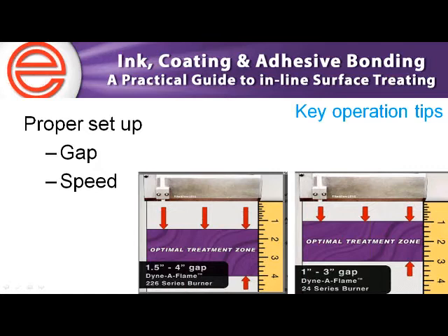It is a higher velocity burner that can accommodate faster line speeds or the jerking that goes on with a robotic application. We want to prevent any kind of waving that could occur with the flame moving at a high line speed. We don't want your part to not be treated from edge to edge, so we've designed this burner for that application.